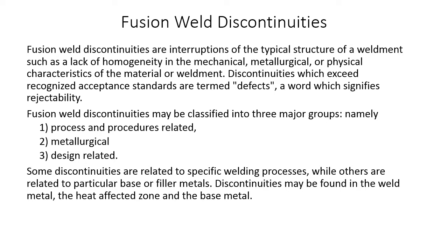The guy in purchasing gets a really good deal on some cheap filler material, and you're stuck with it. So you might be fighting that, or you might just have to chuck it. I've had to chuck whole pallets full of flux cored wire. Something was wrong with the stuff. That heat batch lot number was just bad. So you've got to pitch it. Do your due diligence before you start throwing the money away. But I've had to do that in the past.